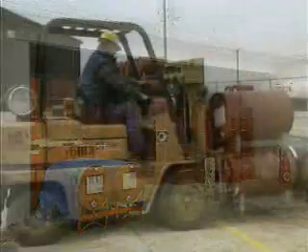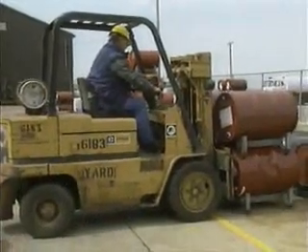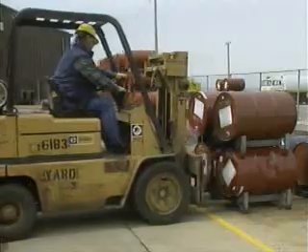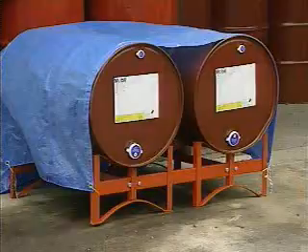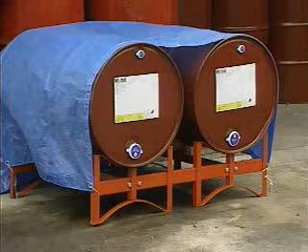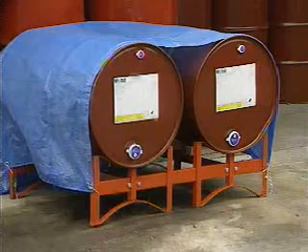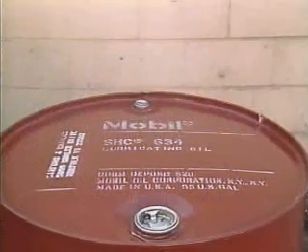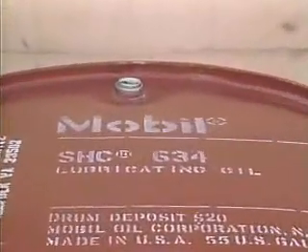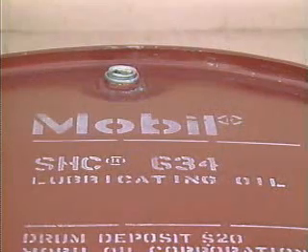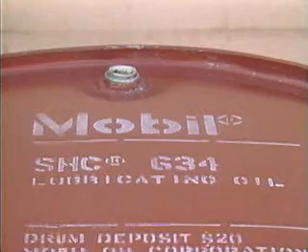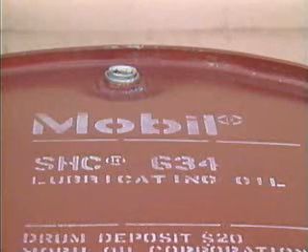from the weather. Generally, metal drums of lubricant should be stored either upright on pallets or horizontally on racks that keep the containers off of the ground. You see, storing a metal drum on a rack keeps the metal of the drum from contacting the ground or standing water. This helps prevent the destructive chemical reaction of corrosion from occurring. In addition, storing a drum on its side prevents water from collecting on the top of the drum. Water that's allowed to collect here can eventually penetrate the seal around the drum's opening and contaminate the lubricant that's inside the container.